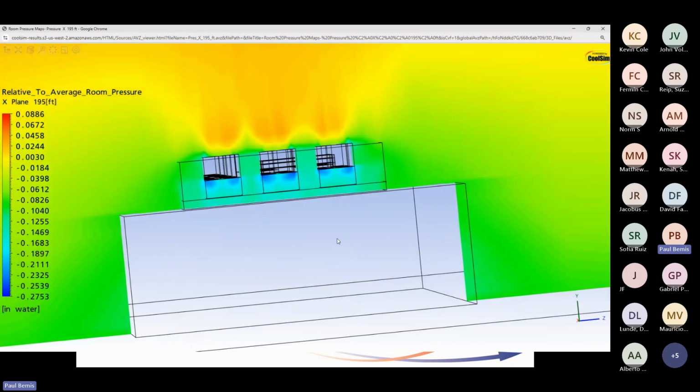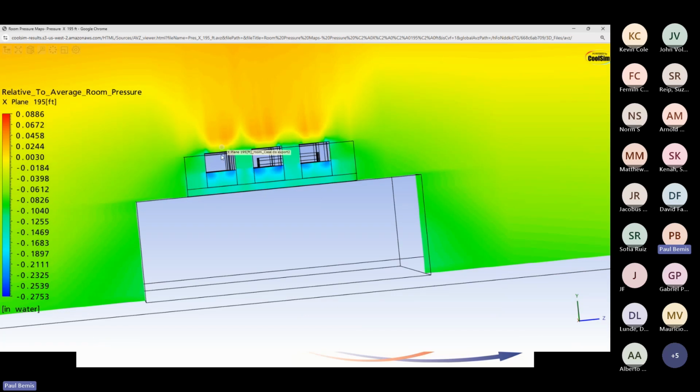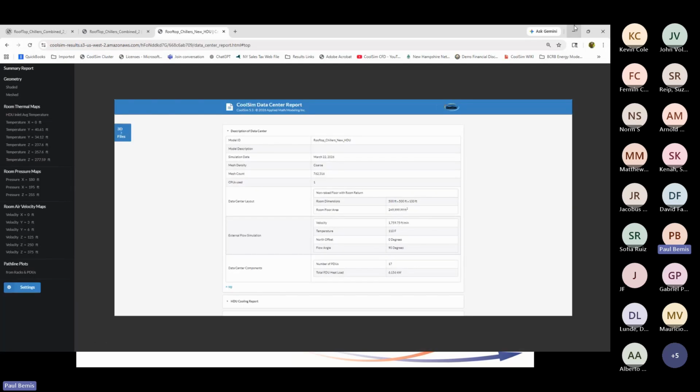And you can see the low pressure is being created underneath those devices that are going to be pulling the air in. So that air wants to naturally recirculate because it's got a low pressure underneath it. And these fans don't have a lot of momentum. They're 10,000 CFM, generally 10, 12,000 CFM each, but they don't have a lot of static pressure. They're just big axial fans. And so they don't really have a lot of juice. They don't have a lot of exit velocity. They don't have a lot of momentum. And that sometimes can cause issues. So I wanted to show you those as well.